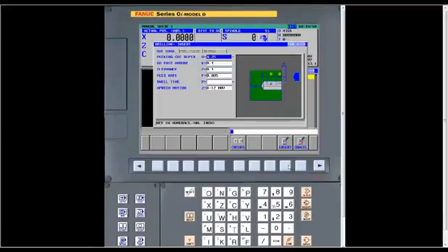And it shows a picture of what it's doing. It also has the Q highlighted. The first thing it asks for is a pecking cut depth. We're on cutting conditions for drilling, and you can see next to this it has an asterisk. Anytime a cycle has a field with an asterisk next to it, you don't have to answer that information. It's optional. But in the example I have here, I did answer that part of it.